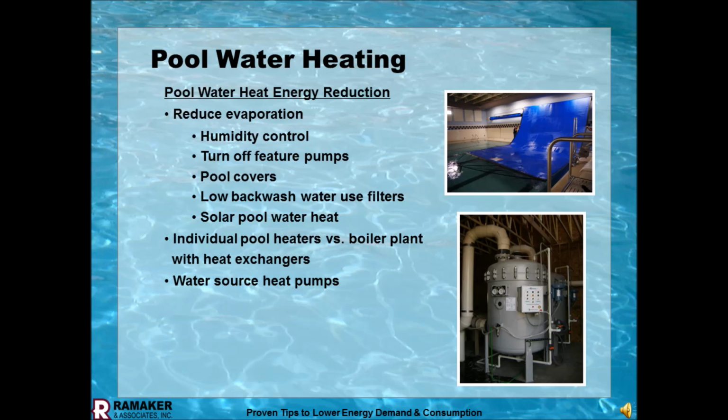On projects that we've done in the Southwest, we did an analysis, and we came back and said that it's so dry here that we're going to be evaporating water from the pools. Instead of taking the water from the pools, how about adding humidity to the air? In other words, adjusting the vapor pressure in the air. If you increase the vapor pressure in the air, the water stays in the pool. If water stays in the pool, it's not doing evaporative cooling on the pool. You're keeping your heat in the pool. It's just a different way of thinking about it. It wasn't the norm.